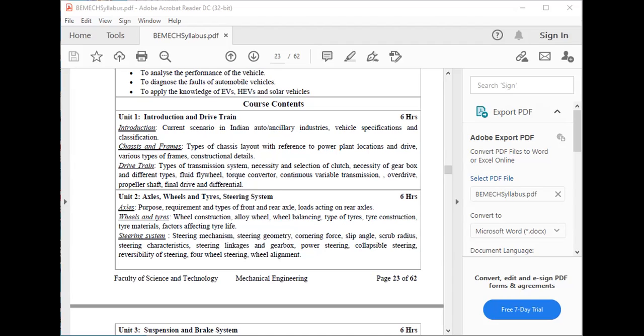Then the clutch linkage gives the right amount of movement and direction without too much pedal pressure. For less wear, we provide this spring to pull the bearing away, and it has to be lubricated. So all this is related to clutch linkages.